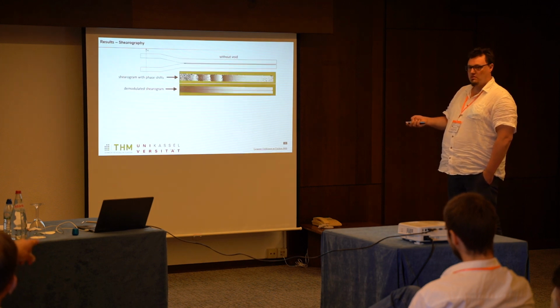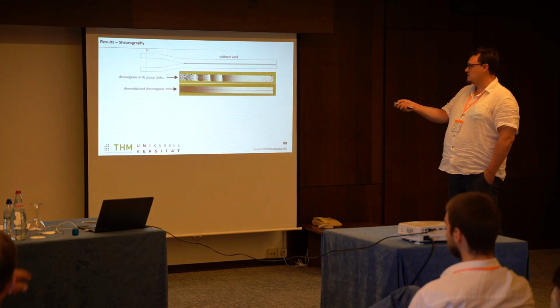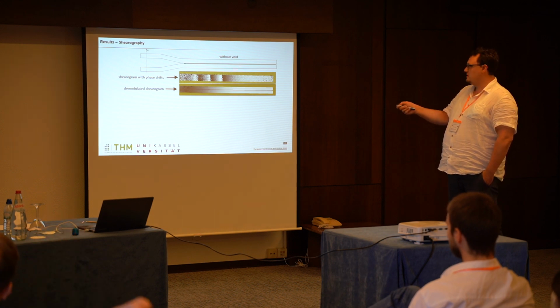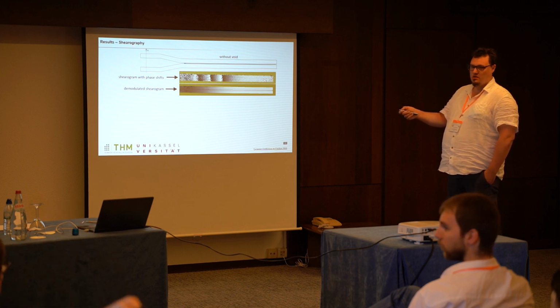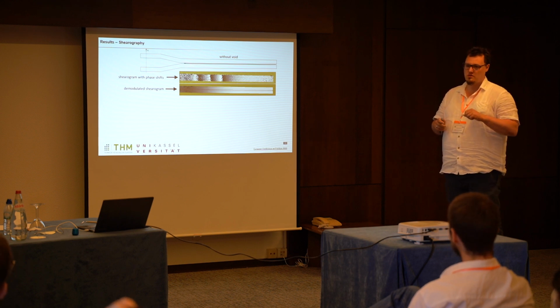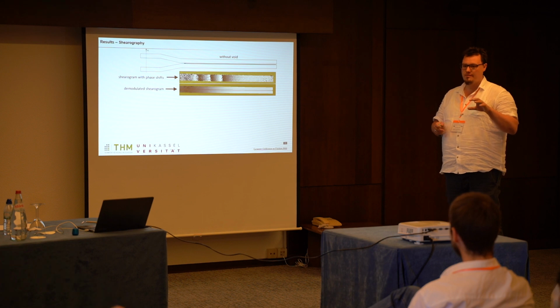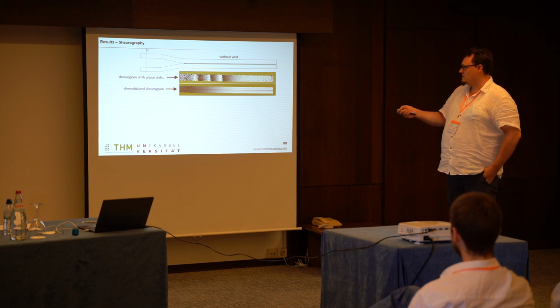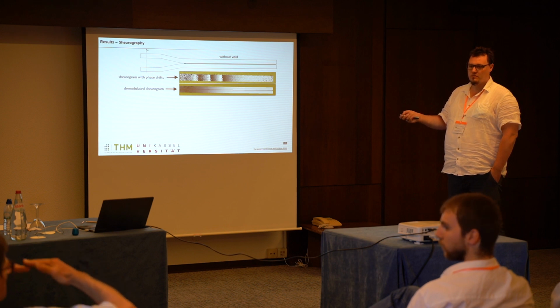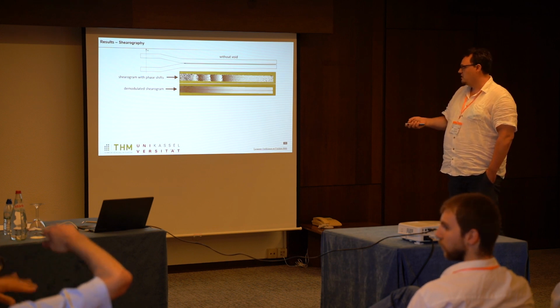The sketch on top. Why do you have a bending moment on the right hand side? We have a force on this side, and the force down the other side. But this adhesive is rubber-like, very soft, with low modulus, and the process zone is very large. There is a tension on the adhesive, and it deforms.